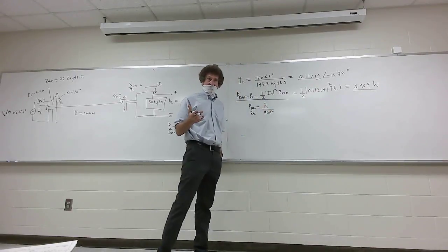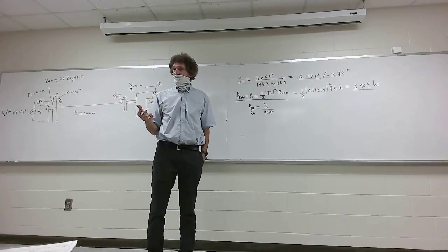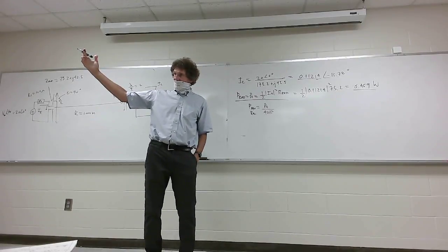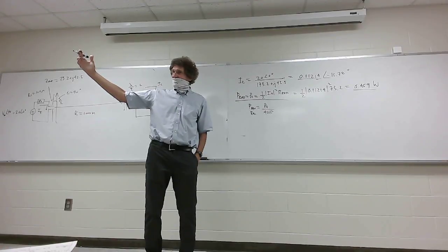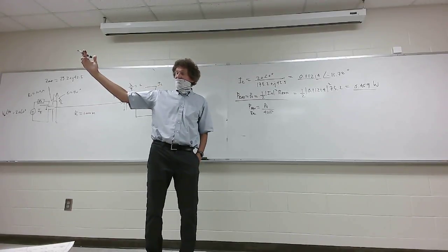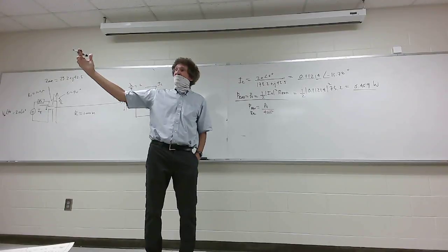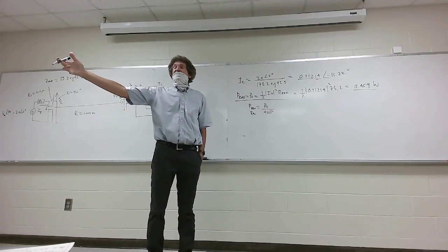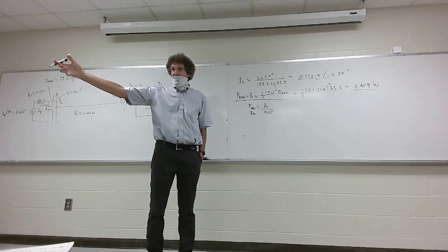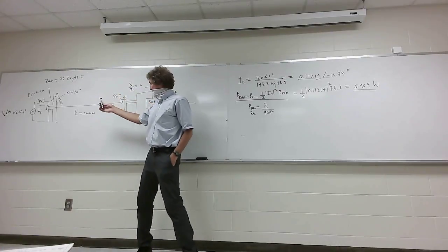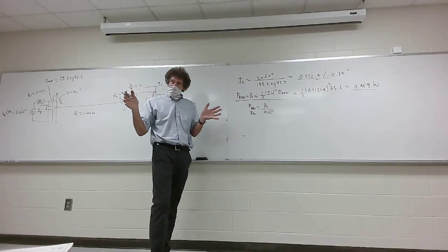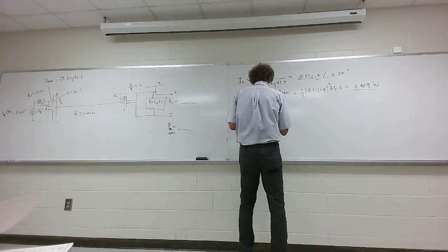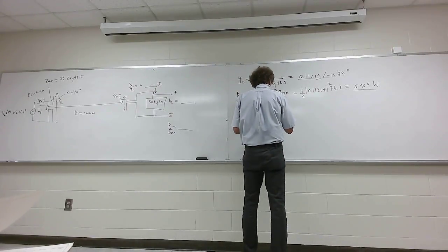Do you all agree with that? And again, that's the isotropic power density at the antenna that's receiving the power, correct? Then what do I do? There's one thing you gotta get right. If you don't know the numbers, don't worry. What do I multiply by? The gain of the transmitter, right? Because we just want the power density here. Y'all with me? So the gain of the transmitter sharpens it. And the gain of the transmitter is 1.64.